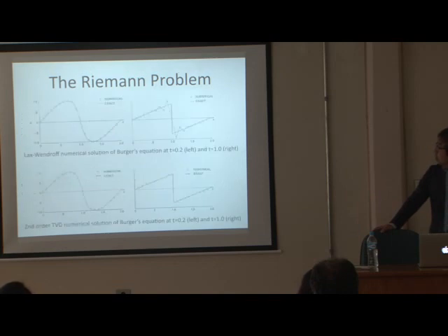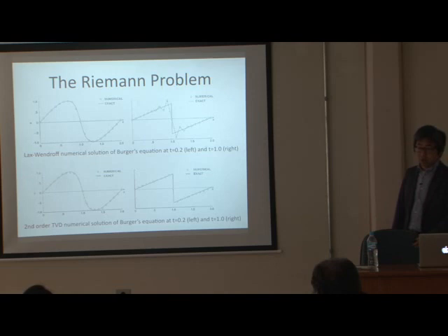So this is another show for the case. This is a Lax-Wendroff scheme, and then this is the second order TVD. The viscosity is included from here. The smooth structure in Lax-Wendroff is good, but the shock structure shows this oscillatory structure. But if you think about the TVD, the total variation diminishing method, we can put on some additional artificial viscosity. We say this is TVD viscosity. We can see the shock structure follows very nicely.